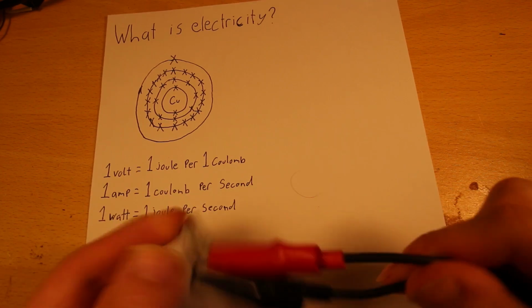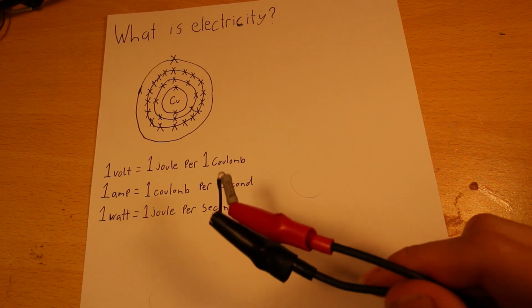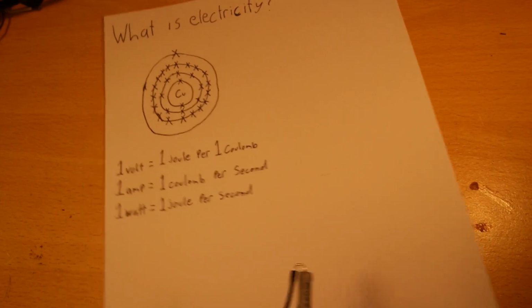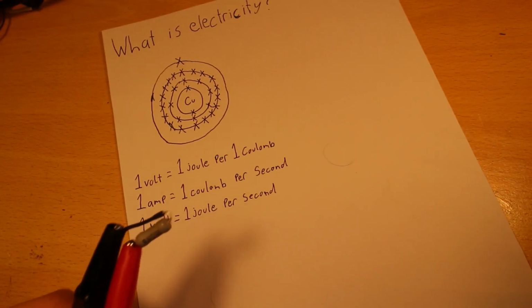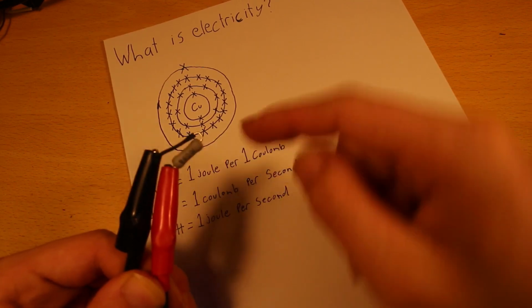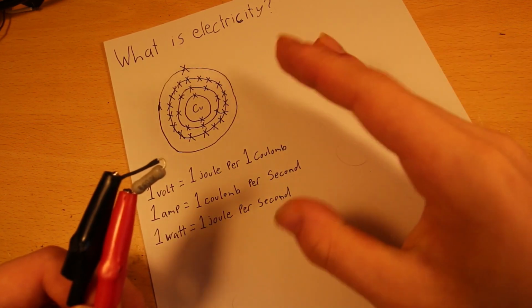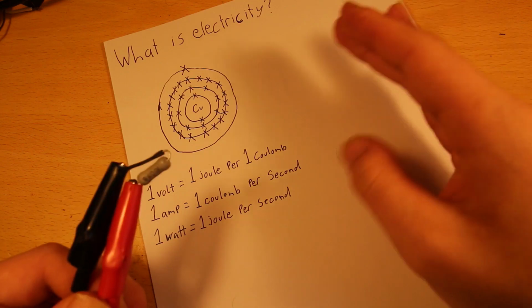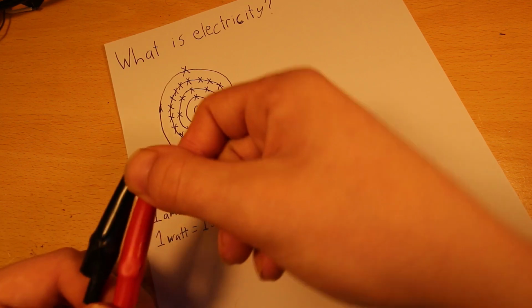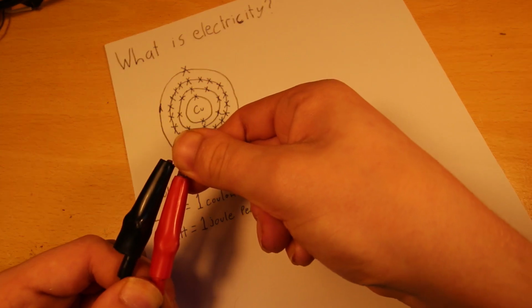This resistor is dissipating the power that flows through it as heat. It's converting the movement of the electrons into heat energy, so it's going to get hot when I run the current through it. It is currently dropping 0.29 volt across it, this resistor. So the pressure is 0.29 and the current is 1. Because volts times amps equals the power dissipation, that means that we have 0.29 watt, 0.29 joule per second being dissipated out of this resistor here, which will make it get warm.